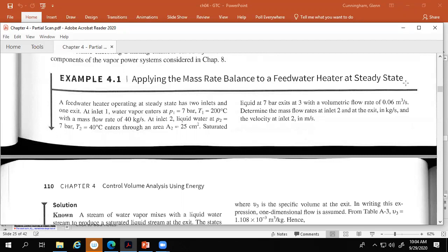And so then the condensate falls out of the bottom of that, and it's initially at that same temperature, but it's way over there, and by the time we get it back to the boiler house here, it's cooled down a lot. And guess what? We didn't get it all back. Some of it leaked, and we got condensate leaks, and we might have some steam leaks. So we got to put makeup water into this thing.